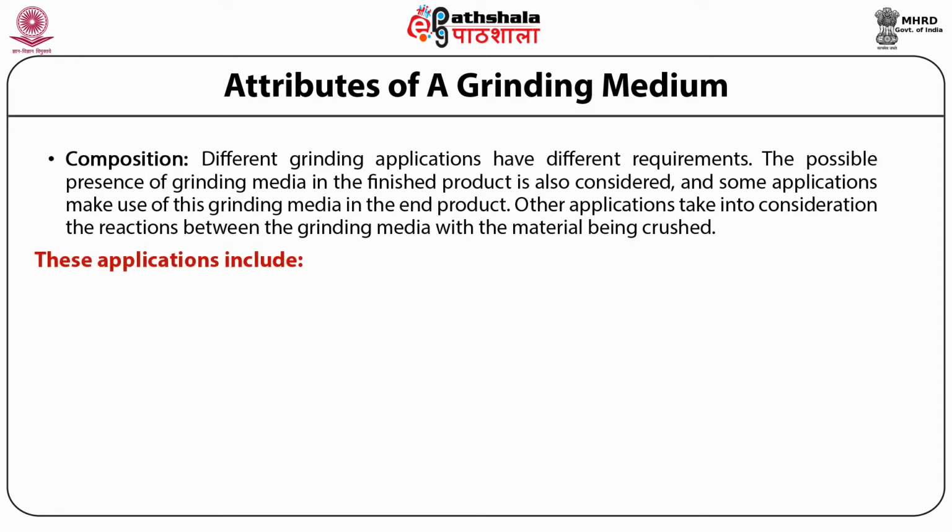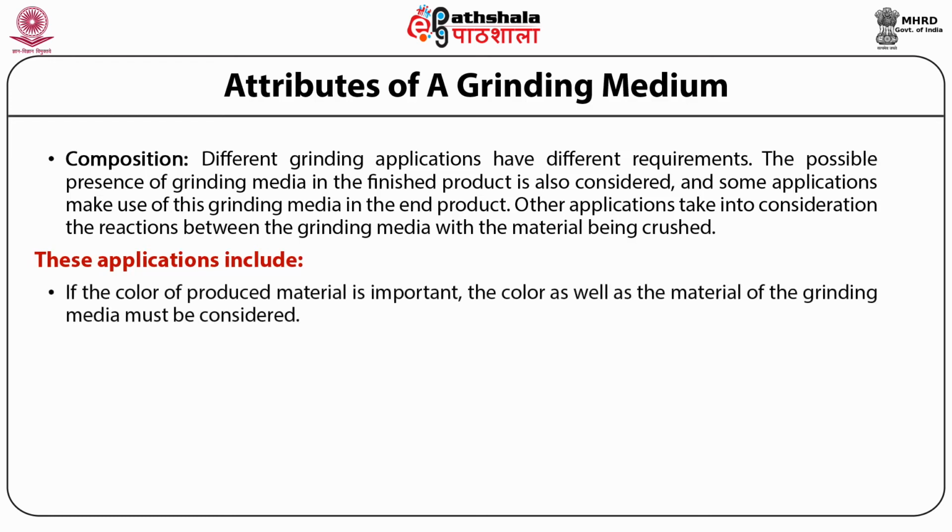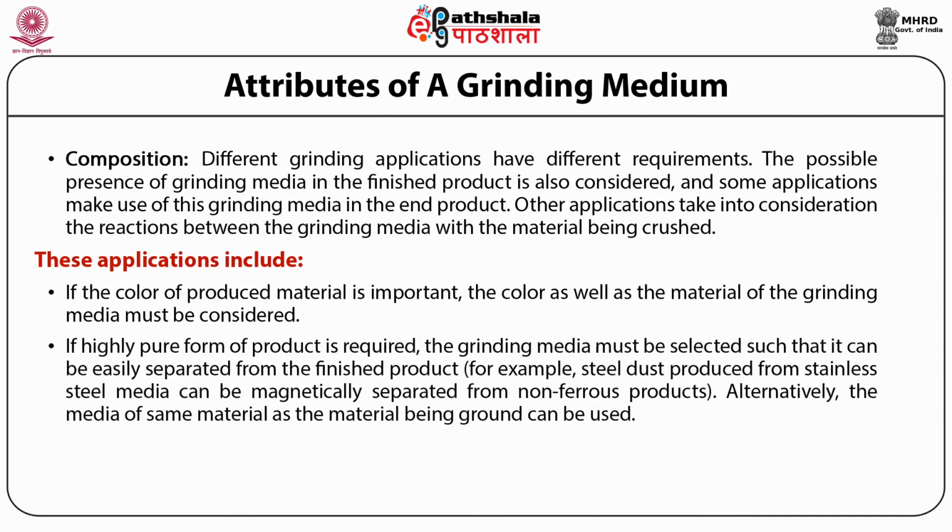These applications include: first, if the color of the produced material is important, the color as well as the material of the grinding media must be considered. Secondly, if a highly pure form of product is required, then the grinding media must be selected such that it can be easily separated from the finished product.